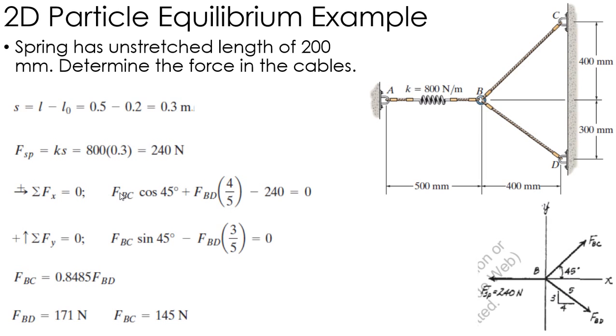and 145. So again, free body diagram, put all my known and unknown forces in there, sum the forces in the x direction, set them equal to 0, sum the forces in the y direction equal to 0, and then solve your system of equations.